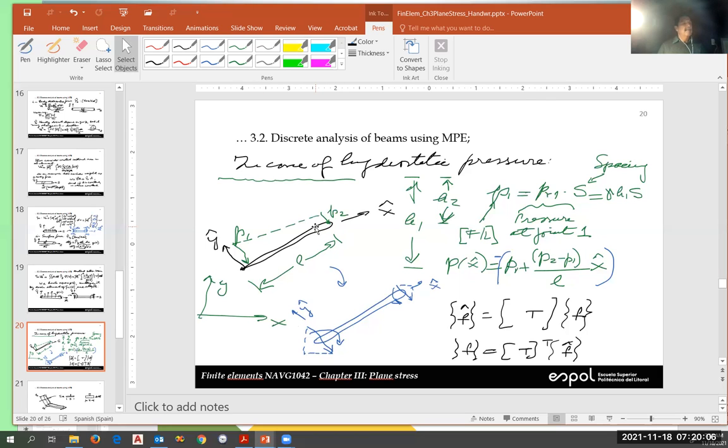We multiply that by the spacing between frames, and this data was provided to you by Engineer Isaac. So we have this product: specific weight, height from the free surface to the point where you want to calculate, and the spacing between frames.